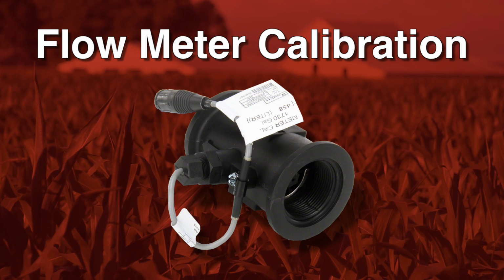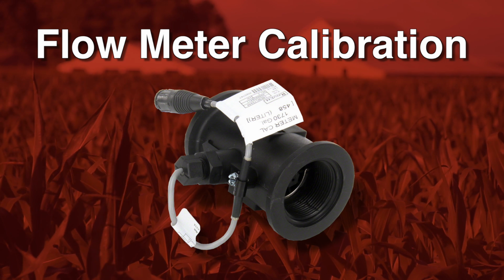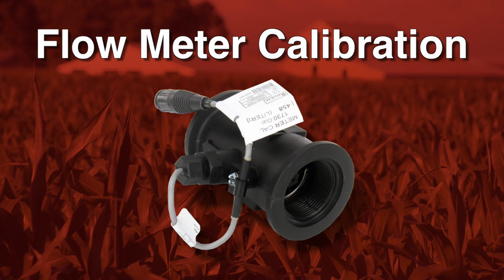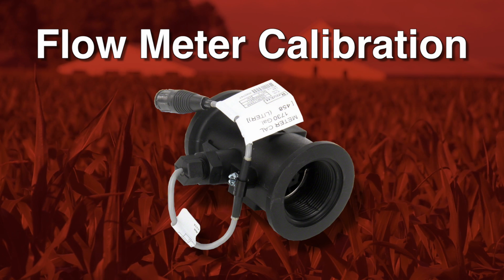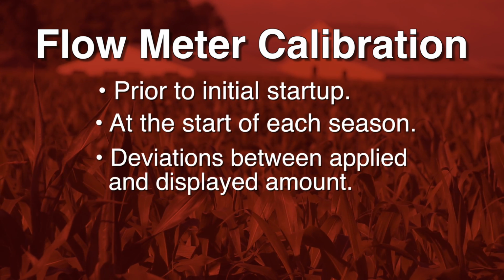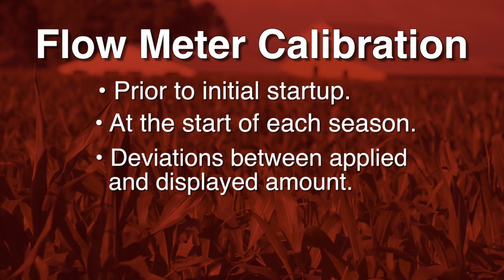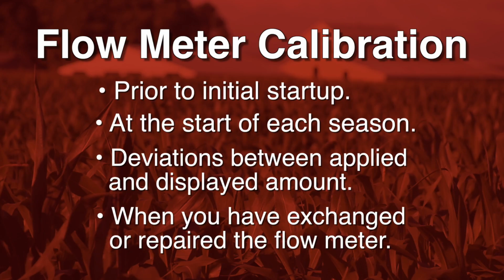The last step in the configuration process is to calibrate the flow meter. The flow meter is used to measure the amount of product applied. Because the number of pulses per gallon can change during the lifespan of a flow meter, calibration must be carried out in the following cases: prior to initial setup, at the start of each season, if you notice that there are deviations between the actual amount applied and the displayed amount, when you have exchanged or repaired the flow meter.